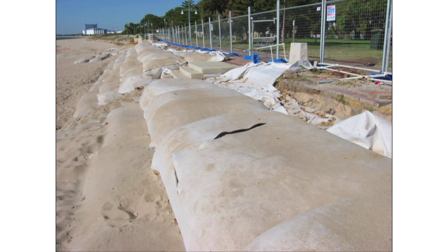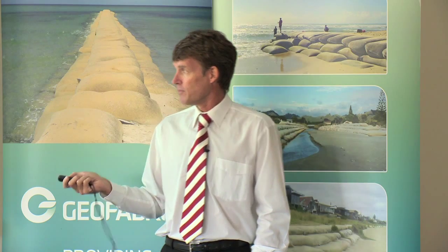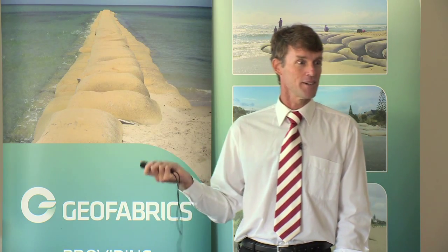The product in that one was a woven product, which is slightly less vandal resistant. Our products, the non-woven staple fiber geotextiles, are also susceptible to vandalism damage. Not as much, but they are still susceptible. The standard materials are far more susceptible. While the cut that you see there is quite large, it can still be repaired at the earlier stages. The moment, though, that you have water going over the top of that and it starts pulling sand out of it, you may as well take that container and throw it out and replace it with a proper container. If you catch it early, you can do repairs on these structures.